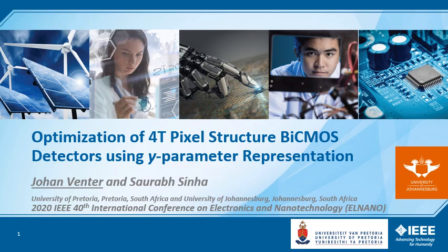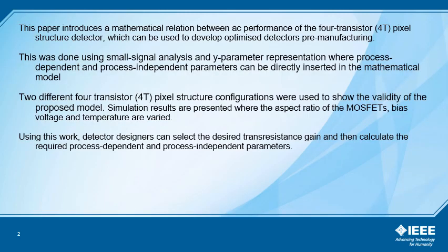I'm presenting my paper titled Optimization of 4-transistor pixel structure BiCMOS detectors using Y-parameter representation, together with Professor Sinha. This paper introduces a mathematical relation between AC performance of 4-transistor pixel structure detector, which can be used to develop optimized detectors pre-manufacturing. This was done using small signal analysis and Y-parameter representation, where the process-dependent and process-independent parameters can be easily inserted in the mathematical model.